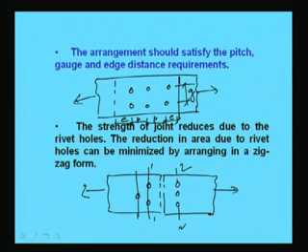in case of section 2 reduction will be due to 3 holes, and another chance of failure will be, say, 1, 4, 3, 5, 1. So, in this way there is another chance of failure. Here also we will see that because of the zigzag riveting, additional strength will come. So, if the reduction is 3 holes also, some additional strength will be added from that formula we know. So, this also we have to keep in mind while designing the rivet.